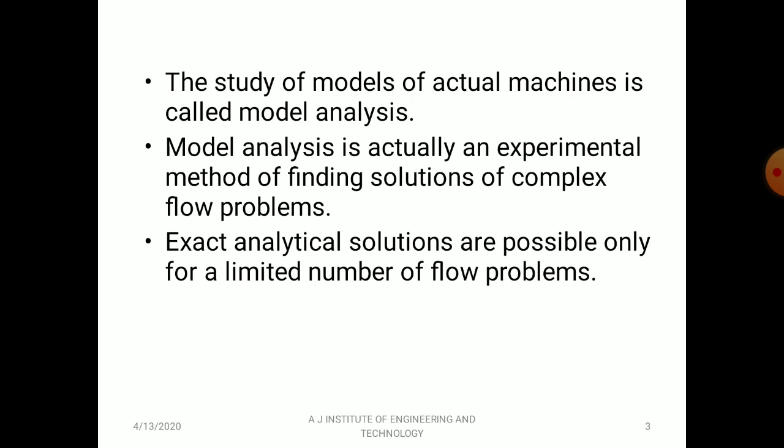Model analysis is actually an experimental method of finding solutions of complex flow problems. Whenever you encounter complex flow problems, you can go for the experimental method. Experimental method in the sense that we go for construction or manufacturing of a small scale or large scale replica of the actual component. Whatever experiment you perform on that model is similar to experimentation on the actual component, that is called the prototype.